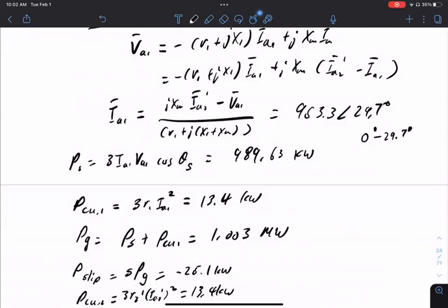For example, there's no wind, or very little wind, but you still want reactive power support. You may just have to cycle active power through the power electronics, which changes the angle, and it comes out the other side. So all that is potentially possible. All right, good. Any other questions?